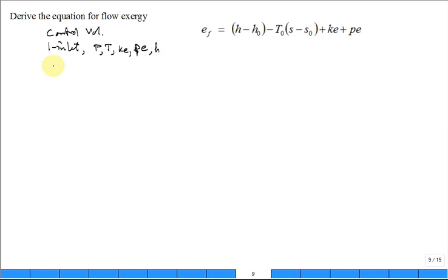It has one outlet, and it's going out at P naught, T naught, with kinetic energy approximately the same and potential energy of 0. Now, if it comes out with an absolute kinetic energy positively equal to 0, how is it coming out if it has no speed? It's got to dribble out somehow. So just say it's negligible kinetic energy. Otherwise it has no velocity, and it's not going to cross the boundary. But it comes out at the dead state.